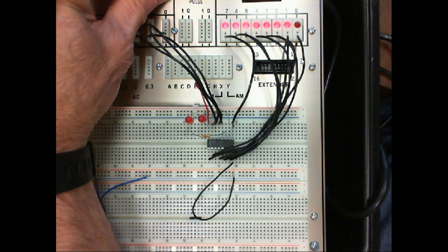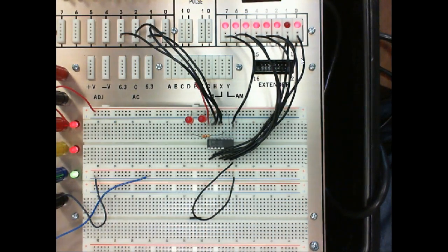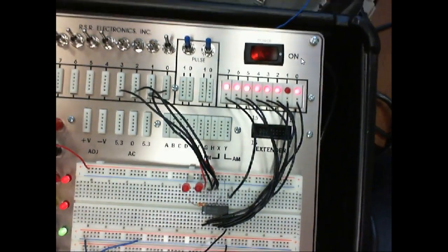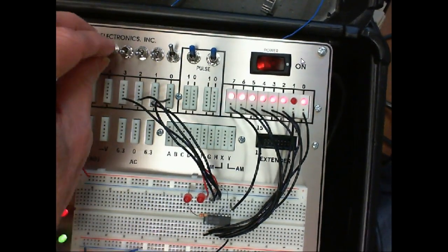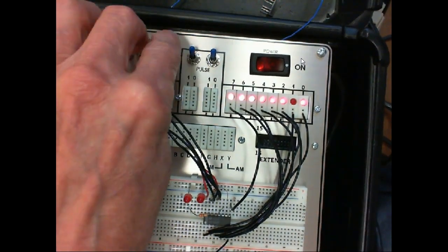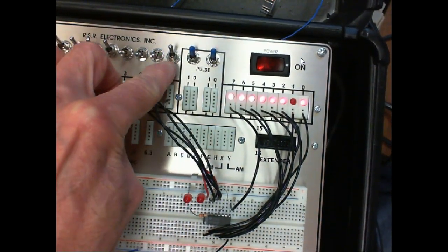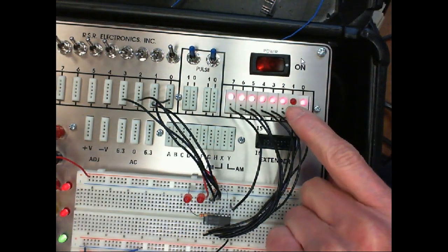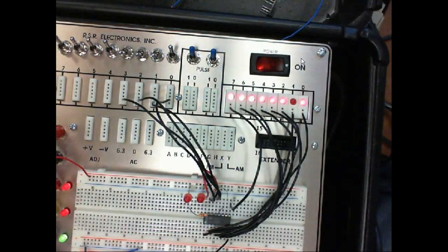This is a BCD 1, so notice the number 1 output went low, and then the number 0 output went back high. So I'm putting in a BCD 1. Let me bring it up so you can see my switches. We're not using these switches. These are the ones that we're using. I'm putting in a BCD 1 and output 1 goes low. Okay, so record this in your truth table.